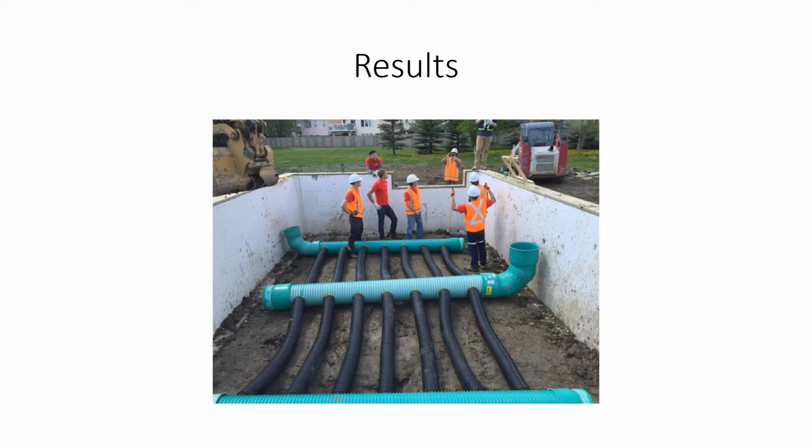After running through all the numbers and optimizing everything, we determined an optimal pipe diameter of 0.3 meters, an optimal airflow velocity in the pipe of 2 meters per second, and an optimal pipe length of 19 meters. With these three values, we do reach that 2.875 kilowatts of input energy that the greenhouse loses, so we can maintain a constant temperature and have the lowest cost of piping.